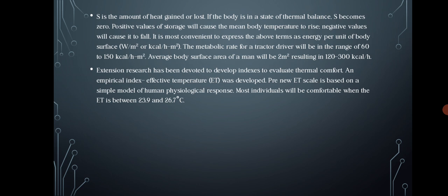Extensive research has been devoted to developing indices to evaluate thermal comfort. An empirical index, effective temperature, was developed. The new effective temperature scale is based on a simple model of human physiological response. Most individuals will be comfortable when the ET is between 23.9 and 26.7 degrees Celsius.